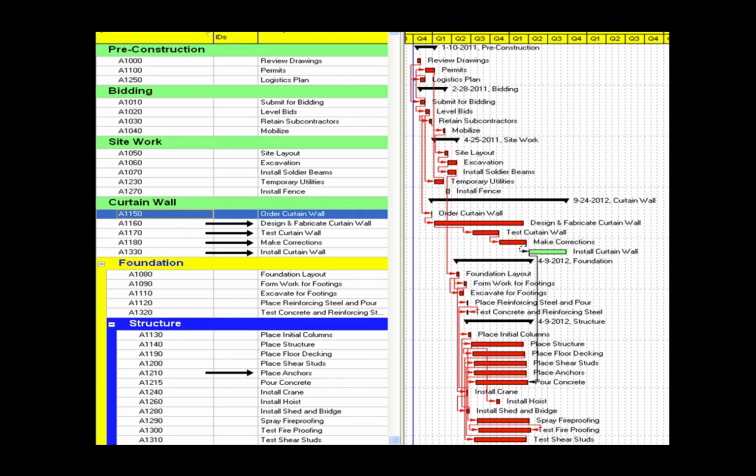So all of these have to be considered. When you're in construction, just because the steel's up and everything's in place doesn't mean you're ready for the next step. Before you pour that concrete for your floors, you've got to make sure that every detail in regard to what's going into that floor is there. Sometimes it's not just reinforcement. Some floors have conduit embedded into them, piping embedded into them. Obviously, these anchors for the exterior walls are embedded too.